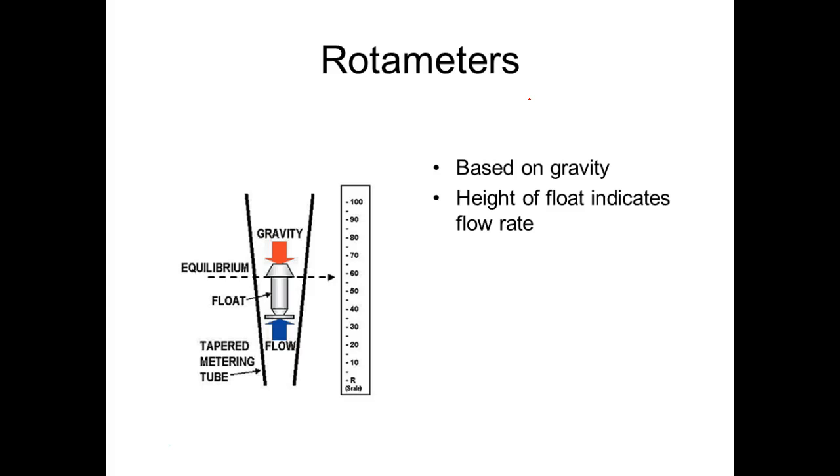This guy here is used quite a lot. My swimming pool had one of these on it until it crapped out on me. It showed me the flow rate of my pump, and it worked just exactly like this. So what happens is the flow comes in. This guy has a certain amount of weight that holds it down, right? You understand, the flow comes in, causes it to lift up, and how far it goes up depends on the flow rate.